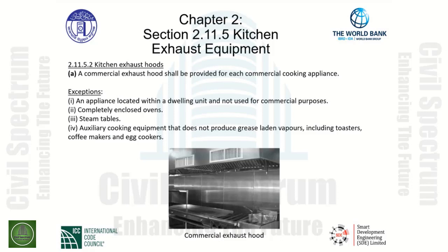Kitchen exhaust hoods are given to us here as a requirement in section 2.11.5.2. Item A, a commercial kitchen exhaust hood shall be provided for each commercial cooking appliance. There are some exceptions, however. The exceptions are an appliance located within a dwelling unit and not used for commercial purposes.